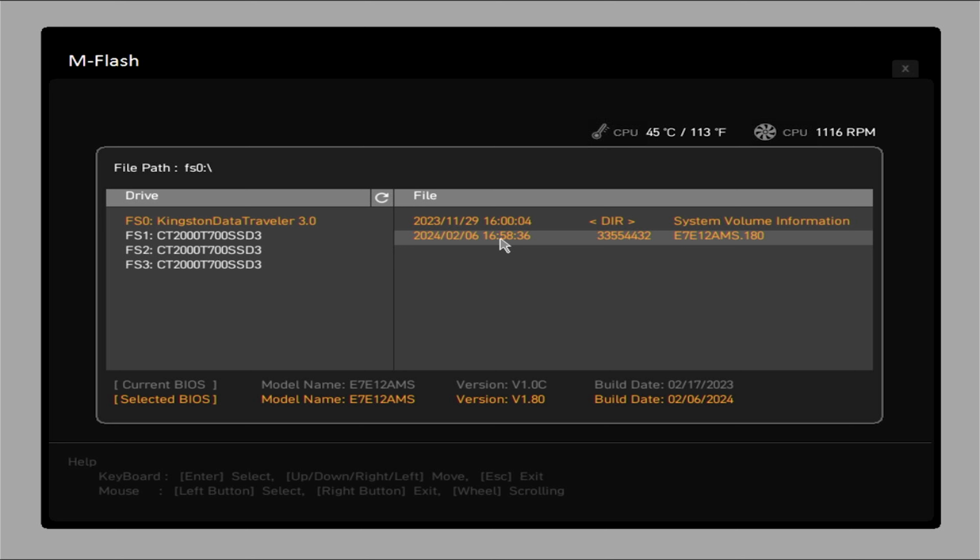Perhaps a bit more useful is seeing what devices are actually plugged into the SATA and M.2 ports. You could obviously do that in other sections as well, but if you find that one of your SSDs or hard disks isn't appearing in Windows, the first thing I would do is come back here and see if it's actually present on the system and it's been detected. If it hasn't, you might want to check your cables or potentially try and test that device on another port or even in another PC. If you still can't get it working, it could have been dead on arrival or something like that. So I'm going to exit out of that one because it's fairly self-explanatory.